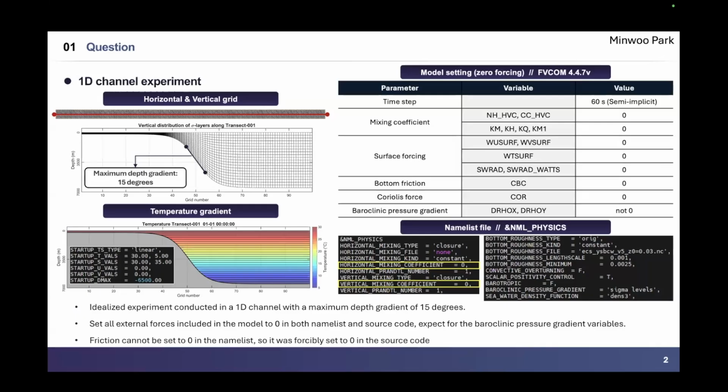Are you really setting it up as 1D? If you only do 1D cases, you have to make sure all cross sections are uniform and do not change. Yes, it is a 3D grid, but the case is a channel case.